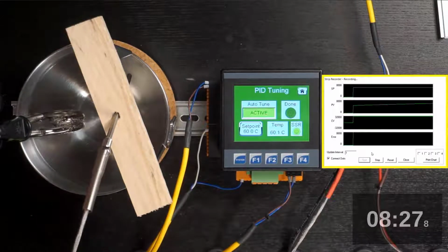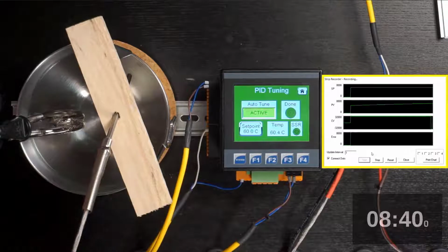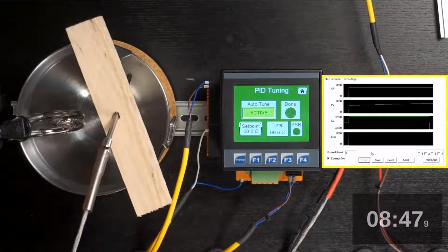Now during auto tuning, you have to get above the set point by a little bit before it actually turns off. You can see in this case, after 0.3 degrees C, based on the scaling, we turned off the SSR. Even though the temperature continues to creep up because of inertia, we are now headed down on the first cycle.